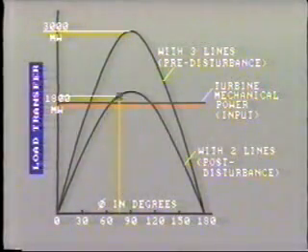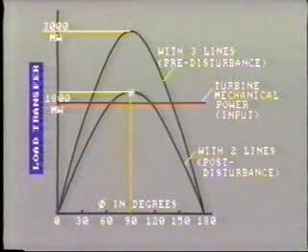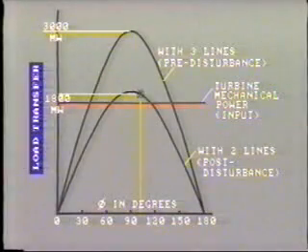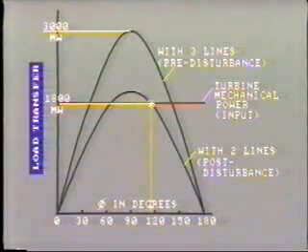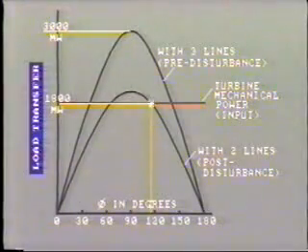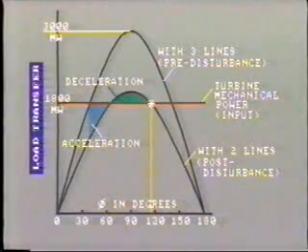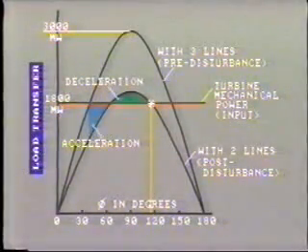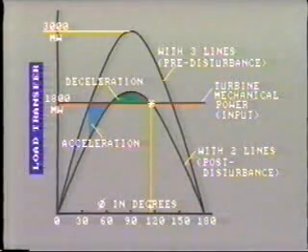As before, the rotor continues accelerating and overshoots and continues to increase the phase angle beyond 90 degrees. At this point, about 115 degrees, the load transfer is once again 1,800 megawatts. But look, this deceleration area above the line is less than the acceleration area below the line.